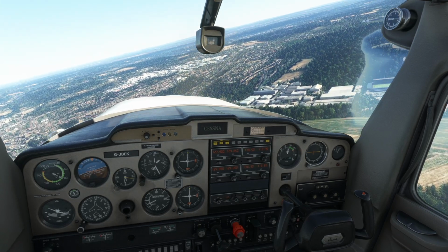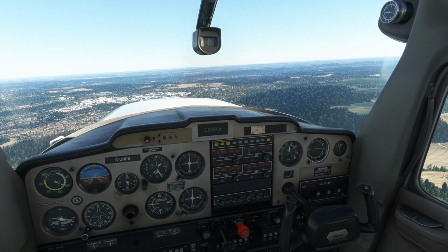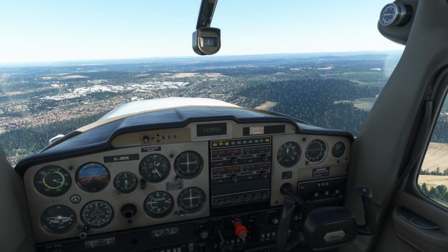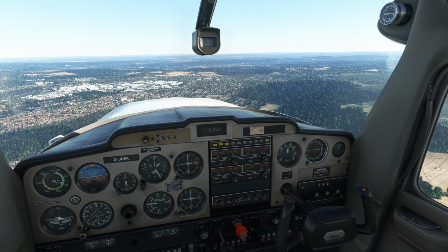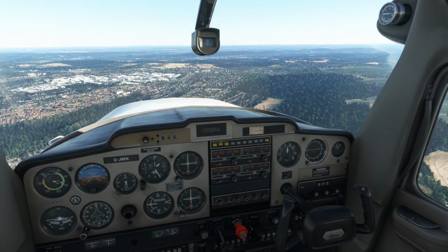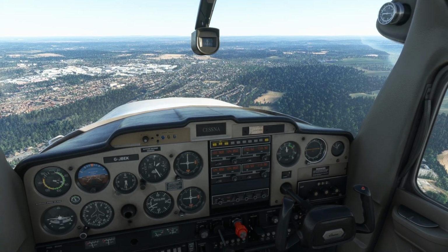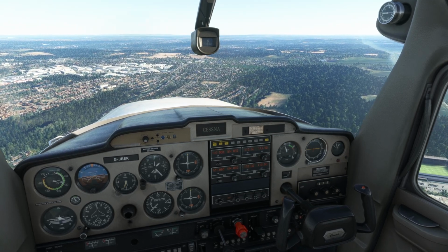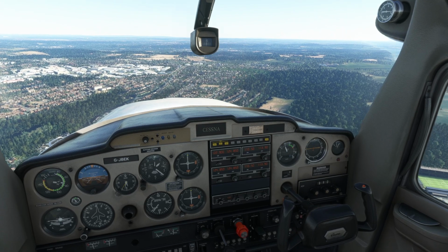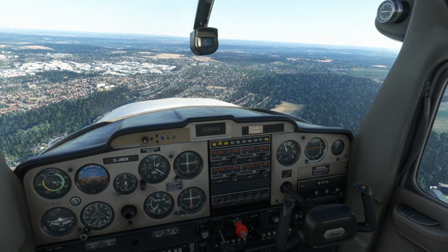So there's 150 degrees. We've lost some speed on the turn on purpose, so then we can extend the flaps slightly, which then give us some drag, and we can lose height. Obviously going into the wind is easier to lose height because our speed over the ground is slower, so we have more time.